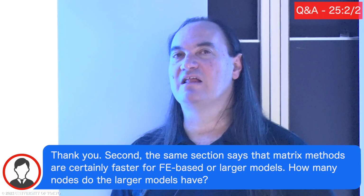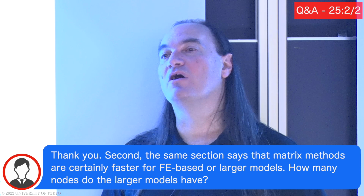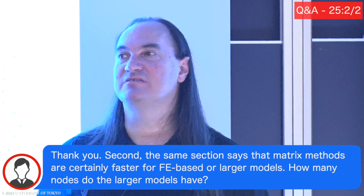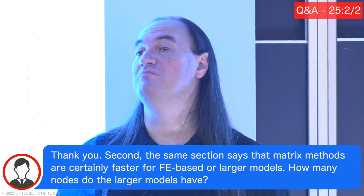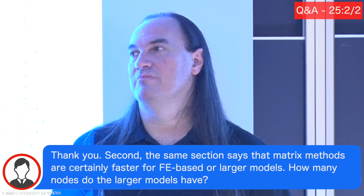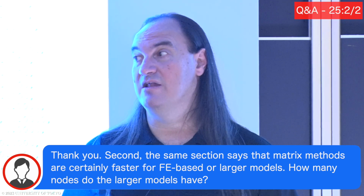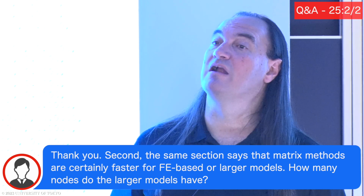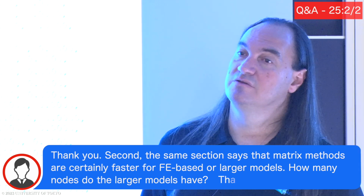When I run the Roman Space Telescope, I think it's somewhere between 150 to 200,000 nodes. To me, it's not as much the node count that's the driver as the number of conductors. The number of conductors makes the model run slower. So I could have 10,000 nodes in a model, but if I have 30 million conductors, it's going to take about the same amount of time to solve as if I had 100,000 nodes and 30 million conductors. So the time to run the model is driven more by the number of conductors than just the node count.